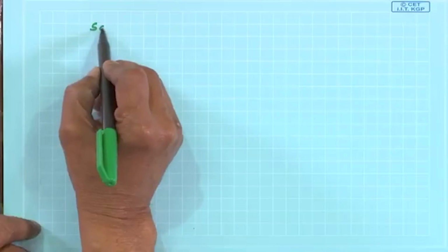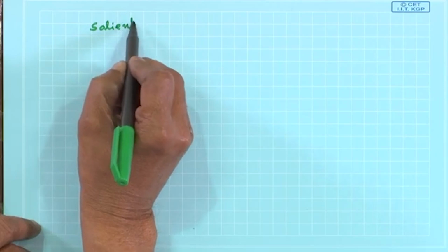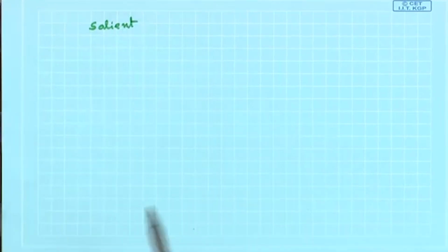Welcome to this salient pole synchronous machine lecture. We have seen that in a salient pole machine we generally don't try to draw an equivalent circuit where you can show terminal voltage, armature current and induced EMF Ef in a single equivalent circuit, because the armature MMF can be anywhere in space depending upon the power factor at which the machine is operating.